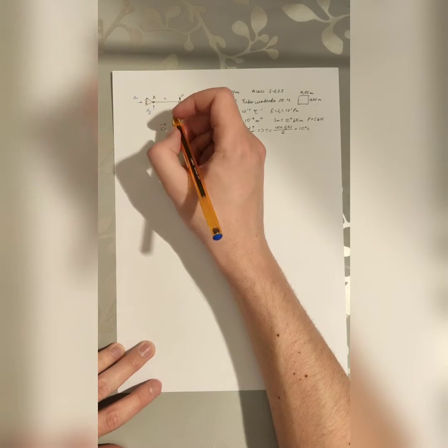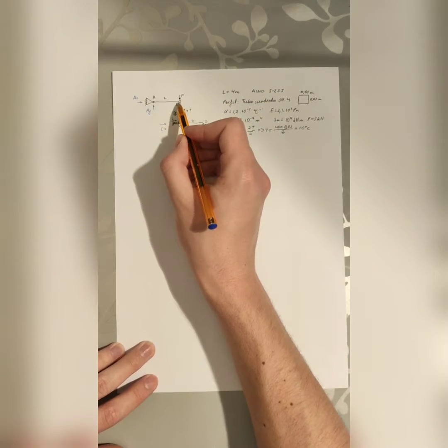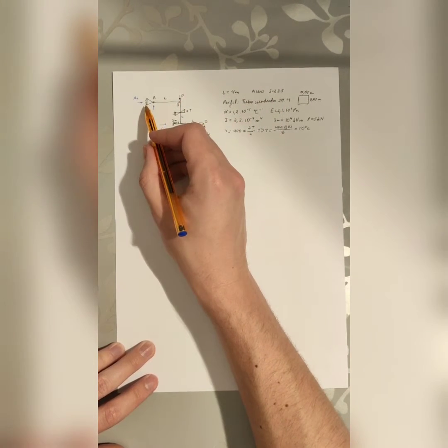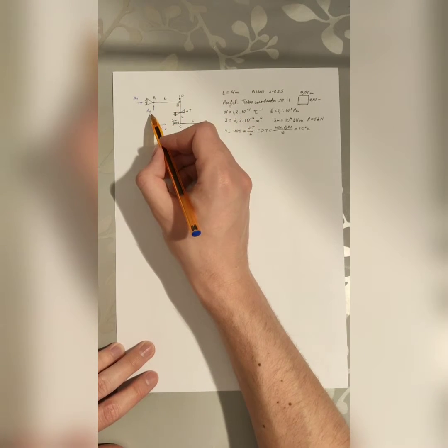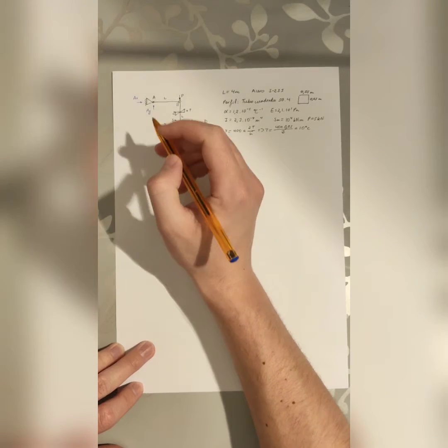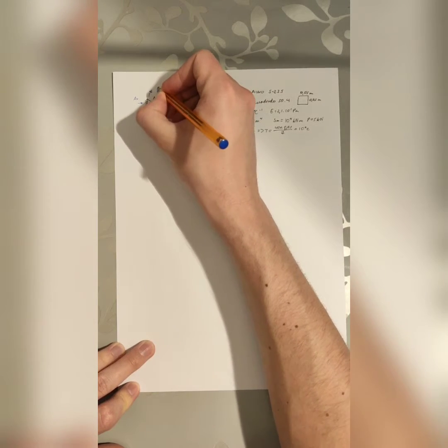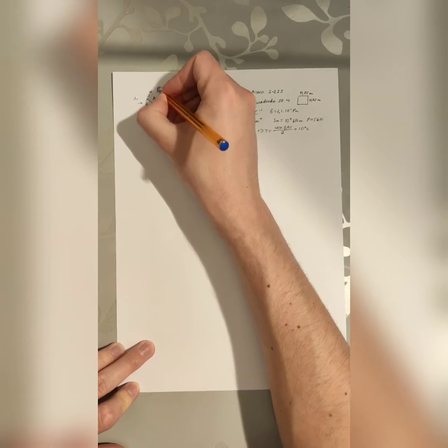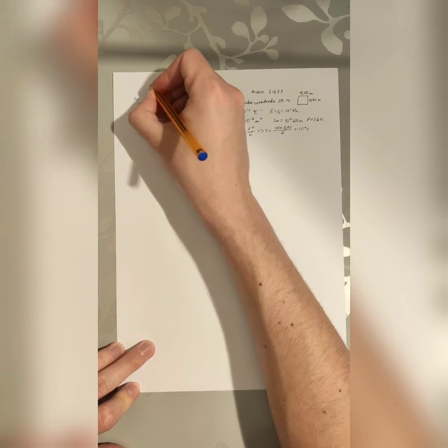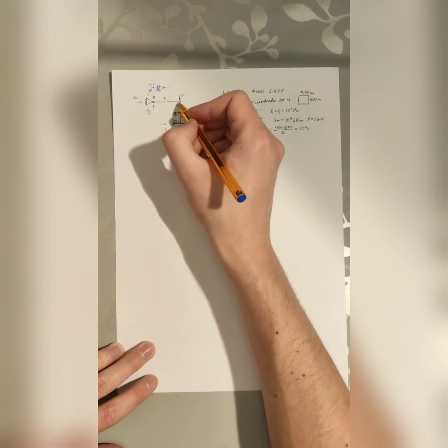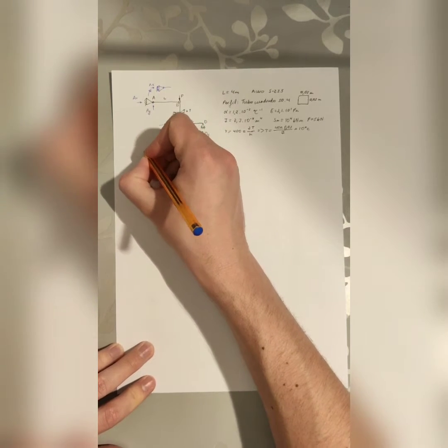The indeterminacy degree has a special thing. Here we have a hinge on both sides. Therefore, we know that there will be no vertical reaction at A. Therefore, this is the same as if we have a roller here, with only AX, because the hinge will not transmit a moment.